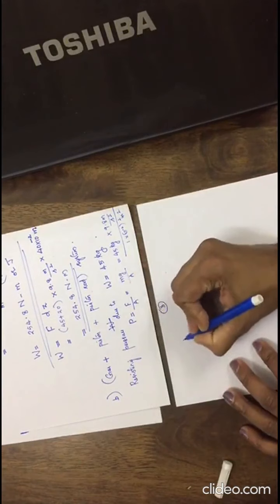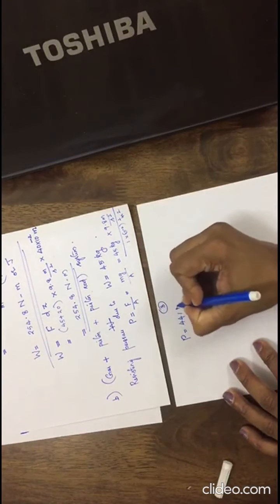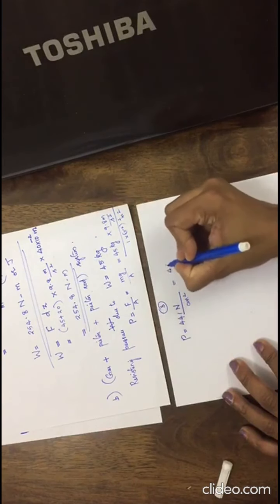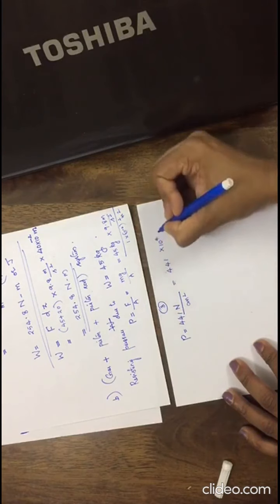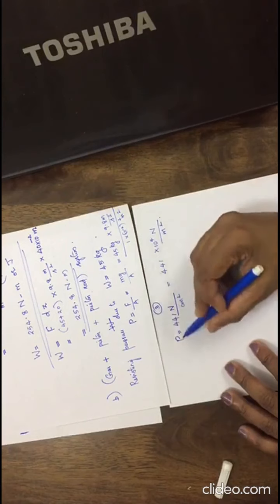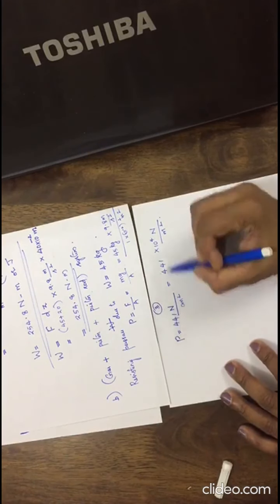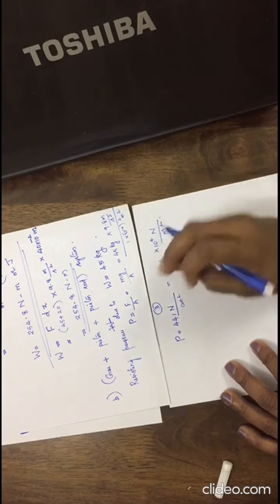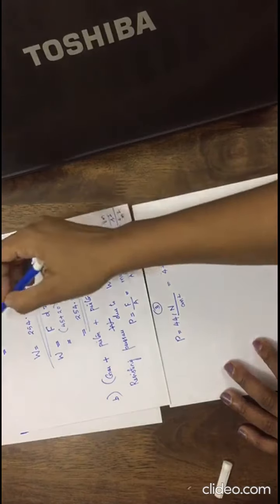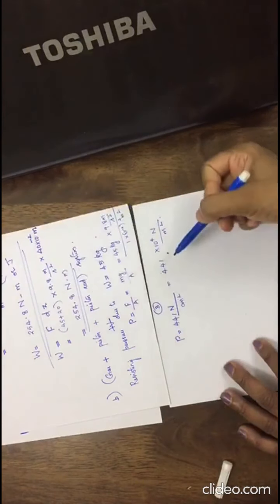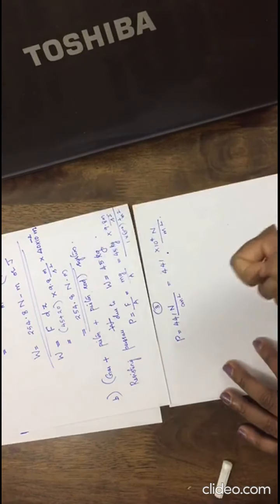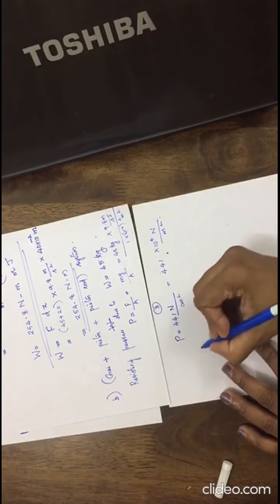So pressure is equal to 441 Newton per centimeter square, which is 441 into 10 power 4 Newton per meter square. So you can see the pressure has reduced to 441 into 10 power 4 when the weight alone is the cause for the resisting pressure. From 637 it has again reduced to 441 because only the 45 kilogram is there to exert a resisting pressure. So how to calculate work?